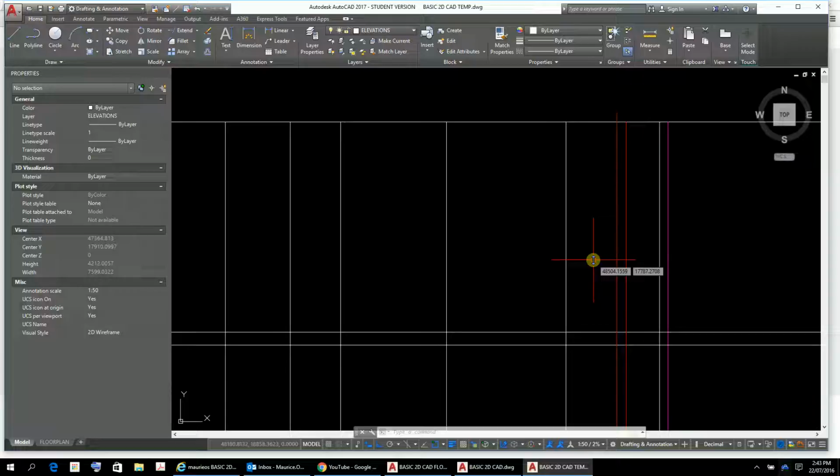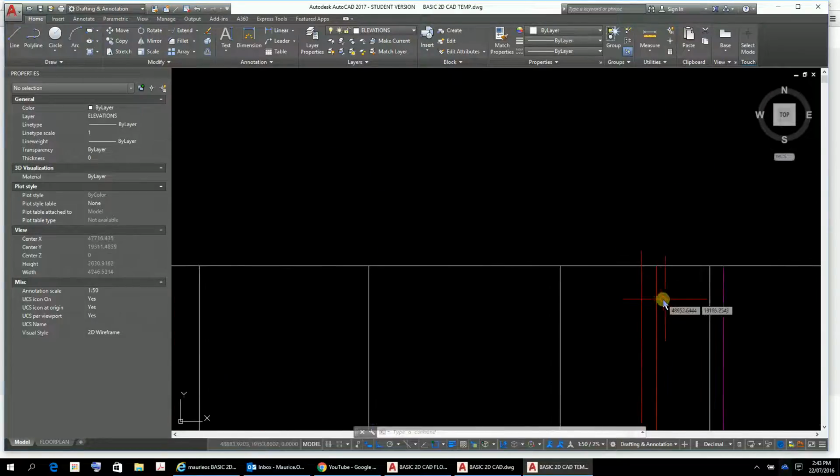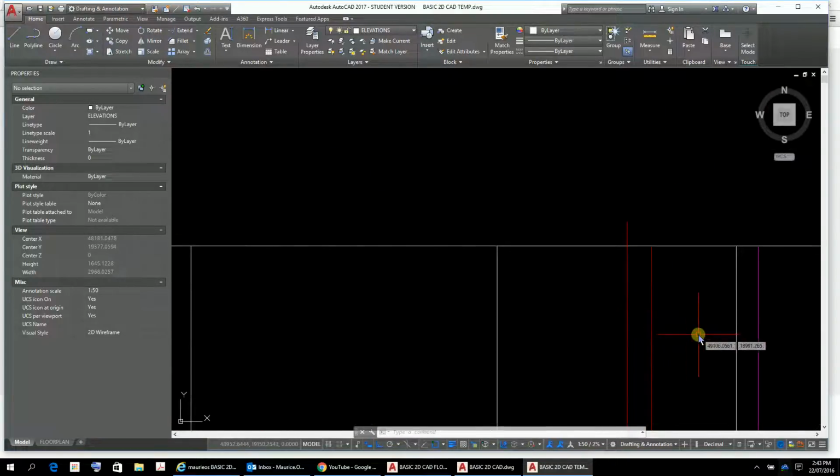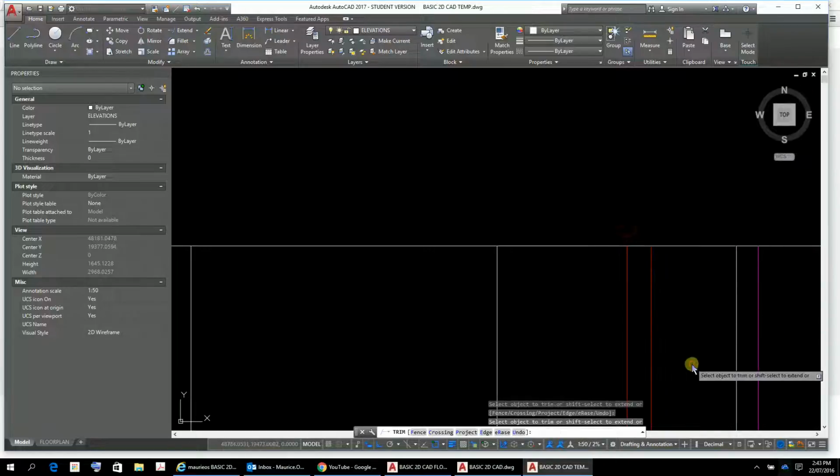actually goes as a 20 degree. That's the bottom of the truss, and it's got the plate on it will be 20 degrees. So what we need to do is get a 20 degree line going up there from there. So I'll just trim that out. Okay, now to get a 20 degree line out there, one of the ways that can do it,